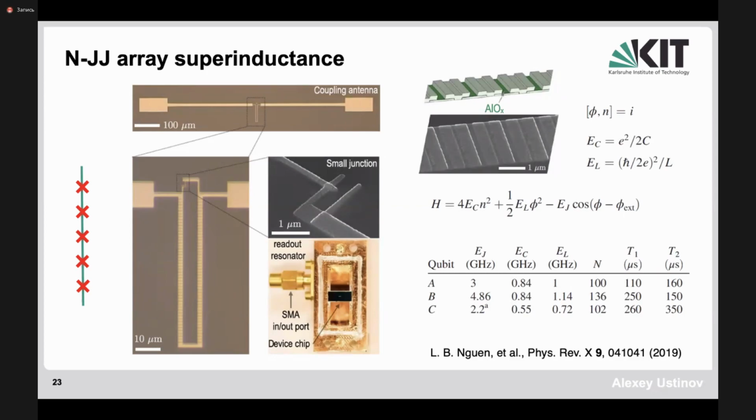One simply uses an arbitrary waveform generator to generate digital profiles at the frequency of the transition between 0 and 1, and then these very precisely generated profiles are directly applied to the qubit. So one saves the additional complication of having an additional microwave source for the local oscillator upconversion.